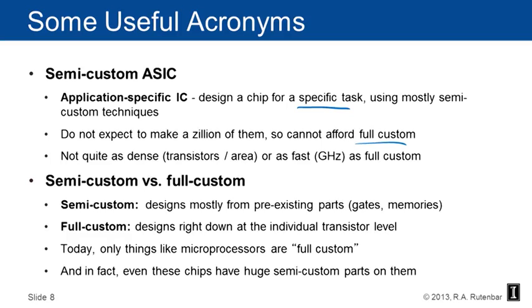If we were to look at the differences between the semi-custom design and a full custom design, what I'd say is that semi-custom designs start mostly from pre-existing parts. So we assume you have a library full of gates that you know how to implement. We assume you have access to libraries of memory so you can put big blocks of RAM down. And we're primarily interested in how we synthesize to those things and arrange those things geometrically to make our design. Full custom designs are really what we say when one does a design right down at the individual transistor level. And honestly, today, microprocessors are about the only things that are really full custom.